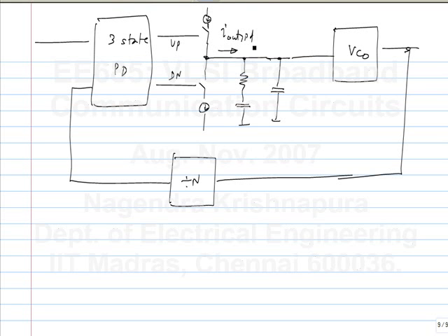How do you find the periodic disturbance? Think of the phase detector as a separate component from the loop filter. I am talking about the periodic disturbances in I out. So the loop filter shouldn't really come into the picture, right? The transfer function of the loop filter. That's how our model is, right?